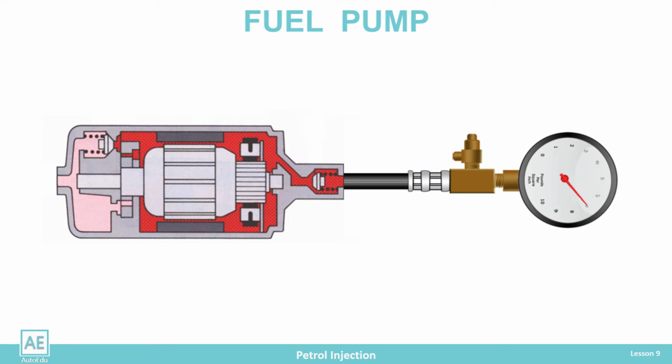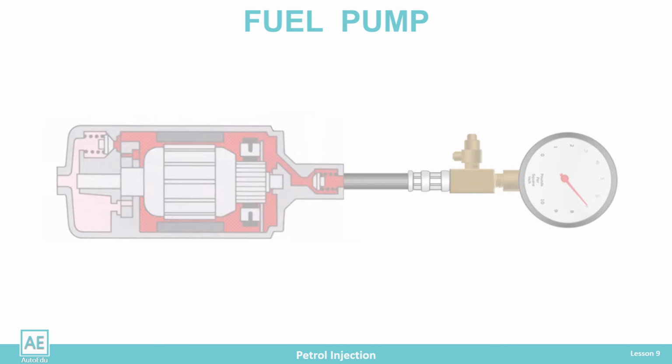The check is done by measuring the fuel pressure at the pump outlet when we close the flow. If the pressure is maintained at 7 bar, then the safety valve is correct, and the pump is good and powerful because it can create much more pressure than necessary.